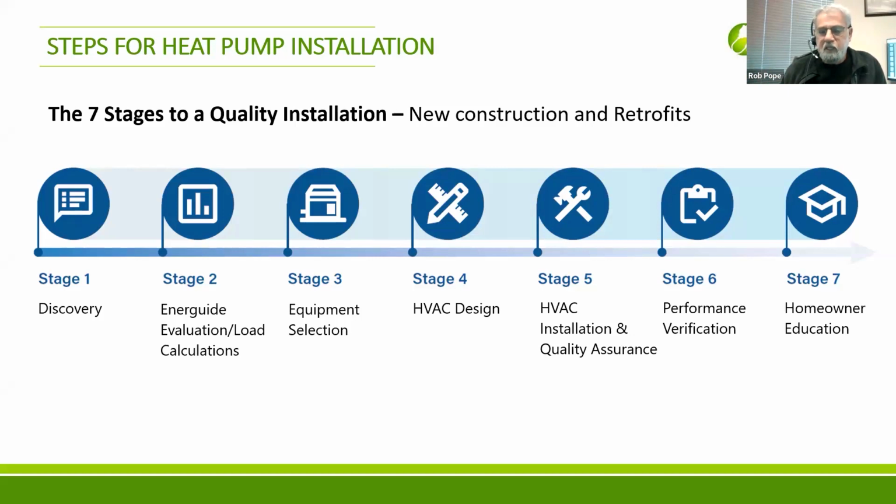There's a few things that are critical in general to all installations, and we'll go into more detail about that later. Performance verification: it doesn't matter how well installed a system is, you have to make sure you do the shakedown. We find out where all the bugs are. If there's anything that needs to go back to the supplier for warranty, you want to know it as soon as possible, and you want to check what you had for performance targets against what you're actually now delivering.